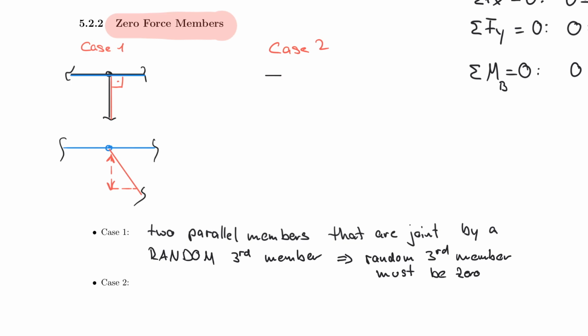That is when you have an external node, so that looks like this, and that is not loaded. So now I cut this one. So I have two external members, and the structure can continue here. Whatever is going on there doesn't really matter. I can maybe draw it like this. The matter of fact is that this is an external node that has no load on it.